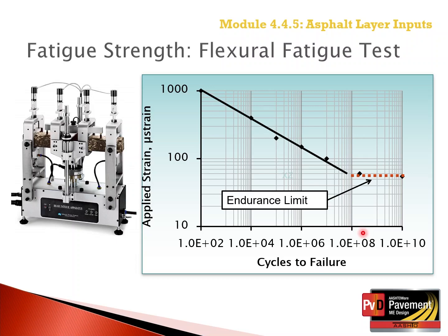Remember at the beginning of this section, the endurance limit was not considered during the global calibration of the bottom-up fatigue cracking transfer function, so it should not be considered or used in design. If the endurance limit is used in the calibration process, then it could be used as a design input for the mixture fatigue strength.